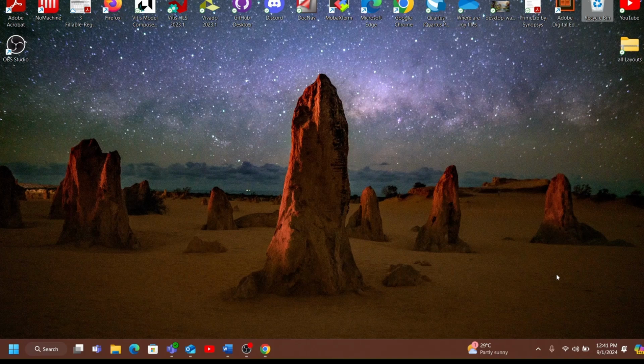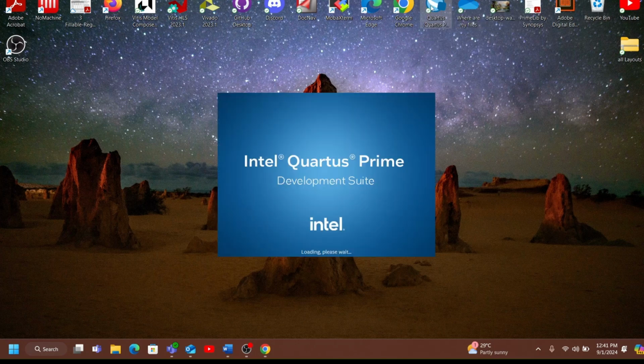Hello, welcome to the starting video in the series for design and analysis of reconfigurable systems. Today we are going to design a 1-bit and a 4-bit full adder in Intel Quartus and simulate it using Questa simulator. Now we can open here the Quartus Prime.